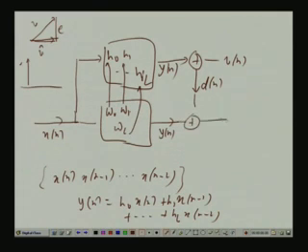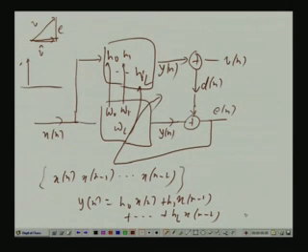Since the optimal filter is not computed directly, it is computed in an adaptive way. So, you put it in the adaptive filter framework, this is Dn, this is Yn, this is En, and use this En in the LMS mode to adapt them. Finally, after convergence, W0 should approach H0, W1 should approach H1, WL should approach HL, and so on and so forth.